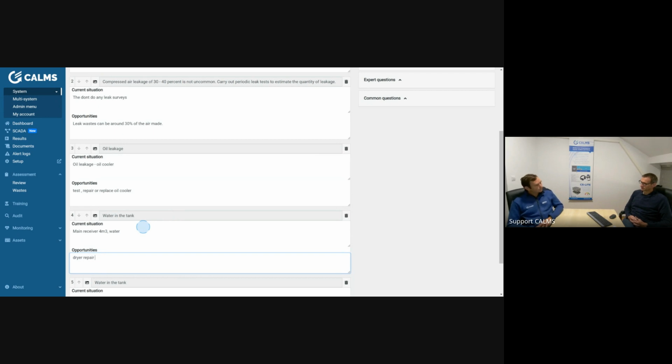Oh, the guy that sold me the compressor here, he told me nothing about the receiver. Yeah, because maybe he is selling you a VSD compressor. Yes, VSD. He said with the VSD you don't need the tank at all. Exactly. That's the same as with the centrifugal compressor. It's always the same. You don't need the receiver. I don't know about centrifugal. I think we don't use centrifugal.